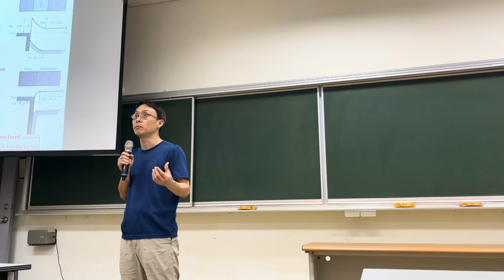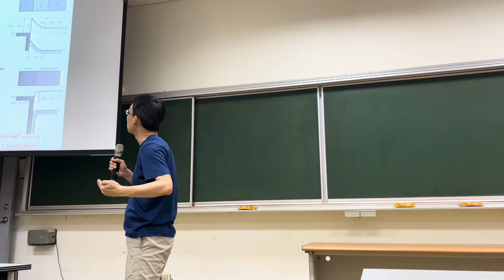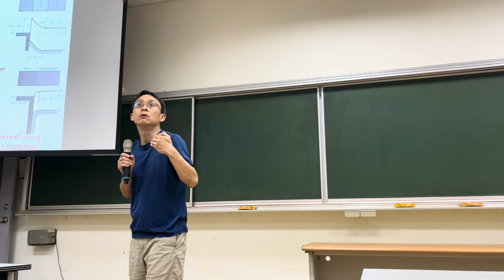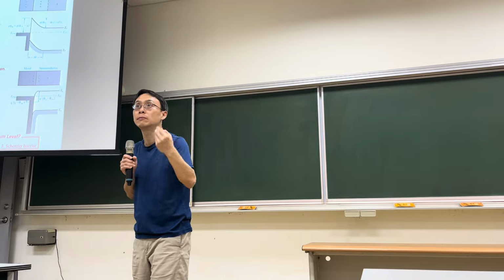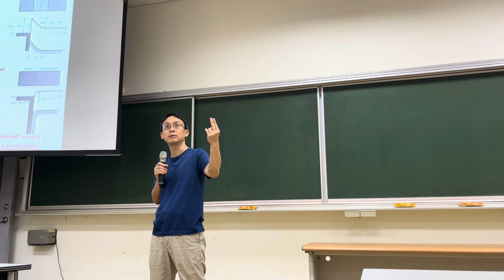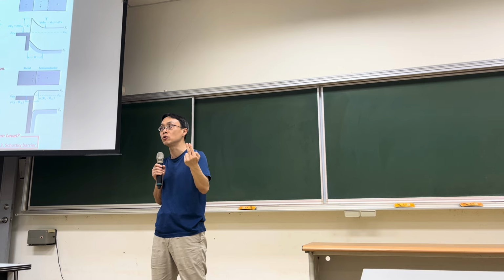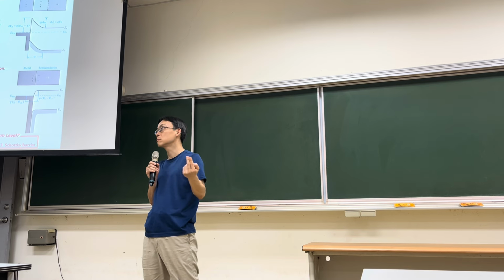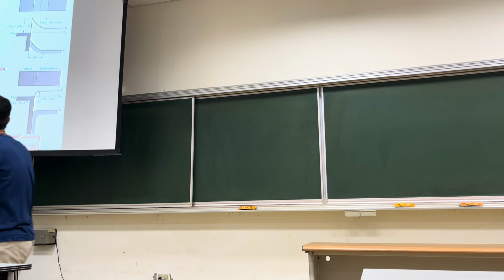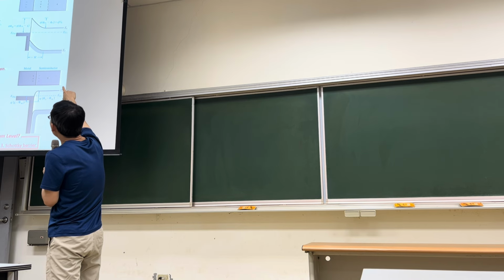big difference, right? Because we can have two types of metal semiconductor interface. So if you want to maximize the injecting the currents from the metal to the semiconductor, which contact should you choose? You have two choices, right? One is to form the Ohmic contact, the other one is to form the Schottky contact. Which one can give you the maximized currents? Schottky, Ohmic. Ohmic, yes. So see, this is the band diagram for the N-type Ohmic contact, right?